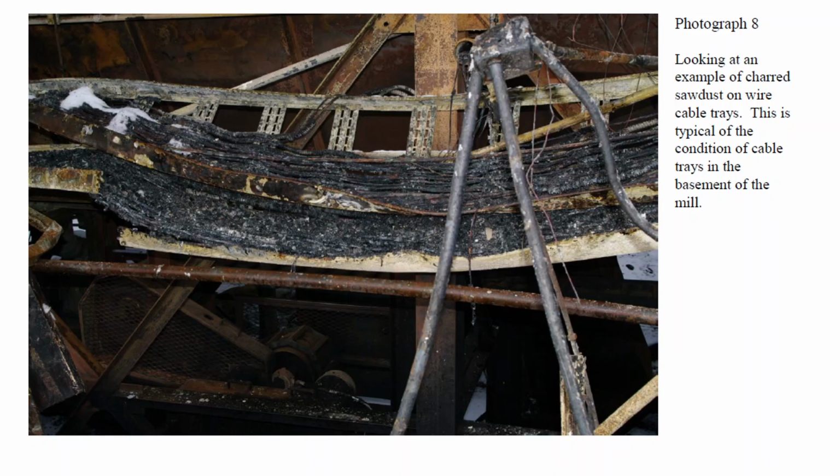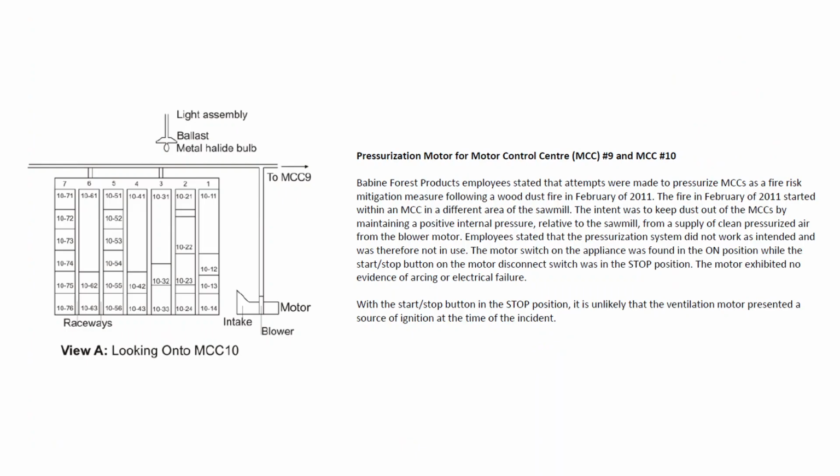And we can see here an example of how much sawdust was left on top of cables inside that particular area. There was a significant layer of sawdust left on top. And so that sort of speaks to the challenge or problem with this particular electrical installation. Now, generally speaking, what happened in this system and what happens in many systems in sawmills is that the MCCs are not explosion rated or dust rated.